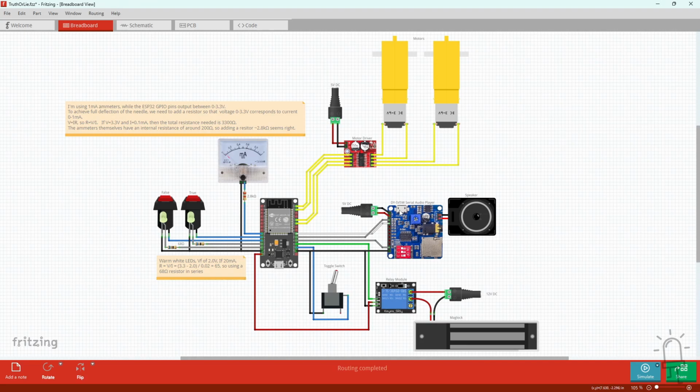Here I've got the MP3 audio player, which is triggered by a serial connection from the ESP32. Now it's a DY-SV5W, which I've mentioned in quite a few previous projects, and it's currently my preferred choice as a way to add audio into props. It runs at 5 volts, but accepts 3.3 volt logic on the transmit and receive line to the ESP32, so there's no need for any additional components here.